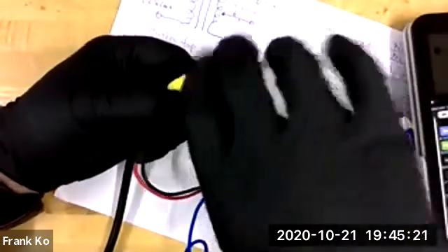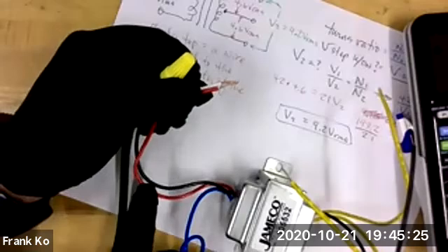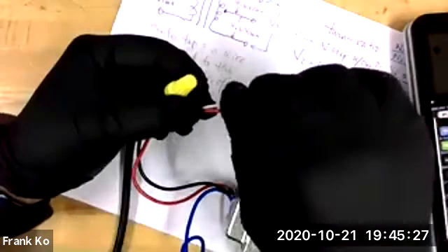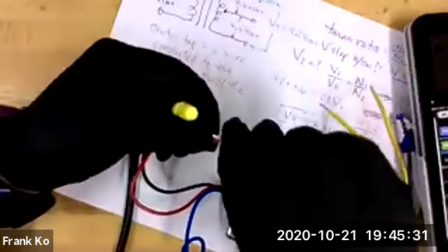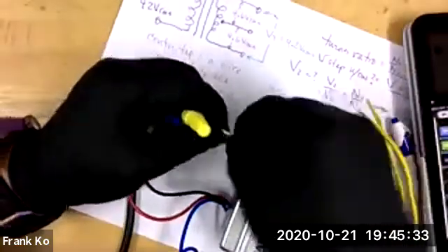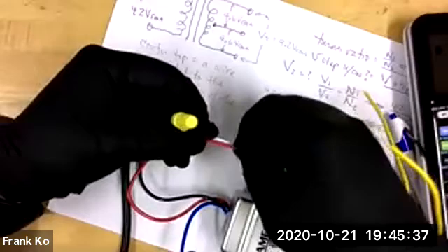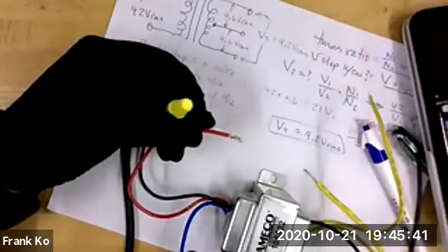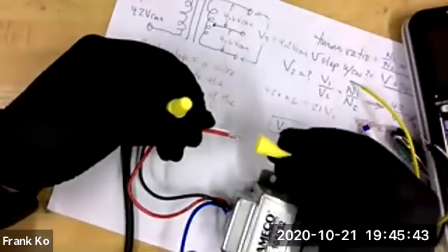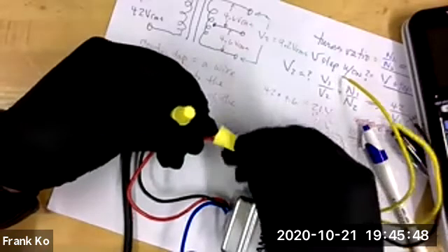All right. So with the remaining wire, the power cord has a white wire, yes? Yeah. And so the remaining wire on that side, let's go ahead and use the red wire and twist these two together, like I'm demonstrating under the camera, like so. Get your second wire nut and cap it and twist. So push and twist at the same time.